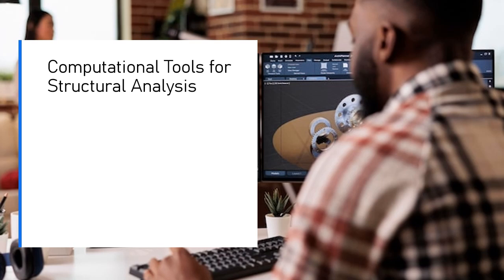The primary challenge was modeling the nonlinear behavior of the cables and deck, particularly under high dynamic loads such as traffic and wind forces. Solution. Using ANSYS, the team created a 3D finite element model of the entire suspension bridge.